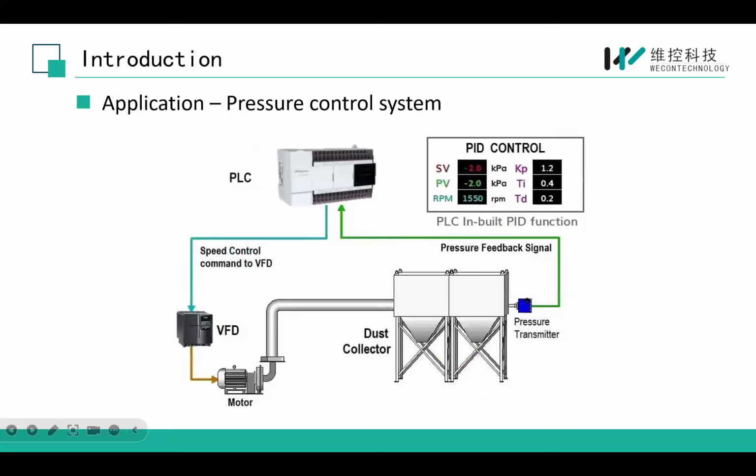And this is another application, pressure control systems. The pressure transmitters feed back the real-time pressure signals to our PLC. And when the PLC executes the PID instructions, it will output and control the speed command of the VFD.